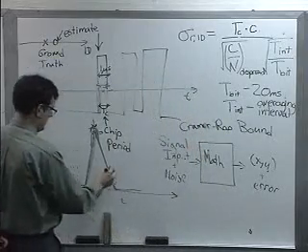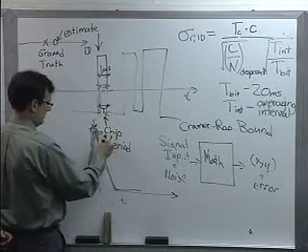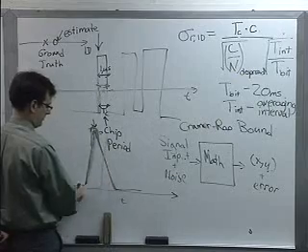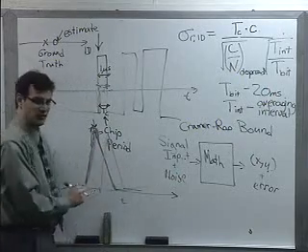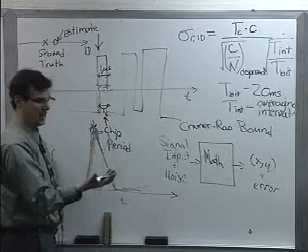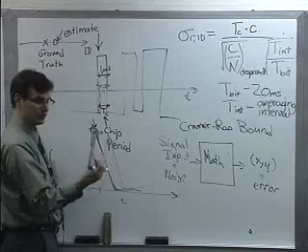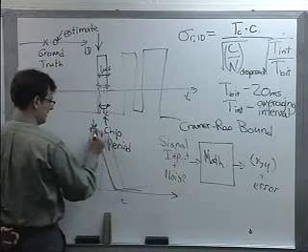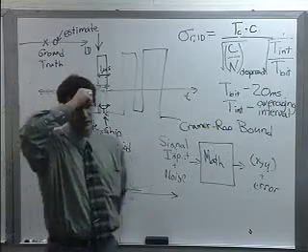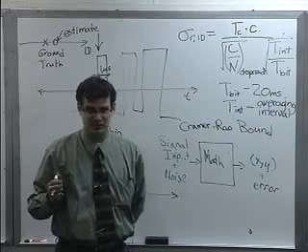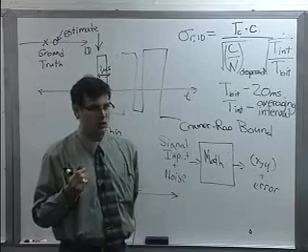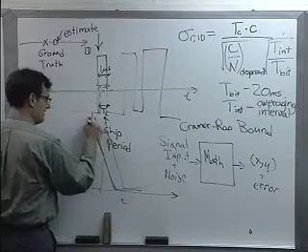Okay. So if you were to delay a chip, you get a correlation that was like that, right? And so if you just sort of bin this out and step, like you were doing a coarse acquisition of a PN code, just trying to see, is there a signal there? You would not expect to be able to tell more than a chip apart. However, there's this device that you can put in, and I think this is done in software now in modern day GPS receivers, but early on there was a hardware device called a delay lock loop, which would basically line this thing up very precisely.